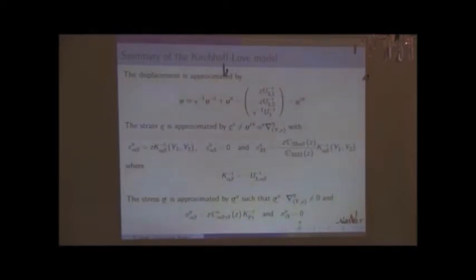Once I have solved this problem, which determines the leading order deflection, I can reconstruct the displacement. I just collect the Kirchhoff kinematics, so the deflection and the rotation, and I can have an approximation of the strain. So I collect the terms. This comes out from just the auxiliary problem we just solved.